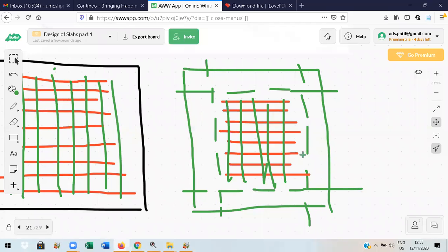In that one, the middle strip is this much. I'll give you the dimensions of all this. Edge strip means all this edge, a continuous edge, peripheral. Whatever edge strip is there, we don't need more steel here. We need less steel. That is why it is more economical than a one-way slab.